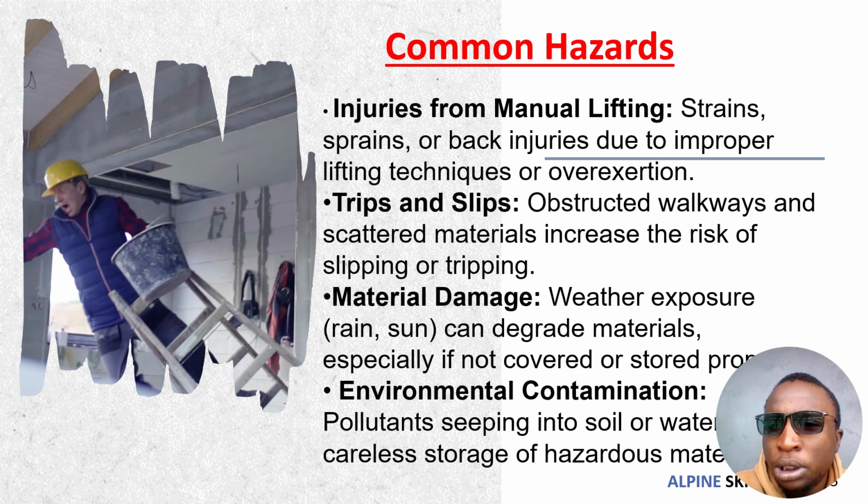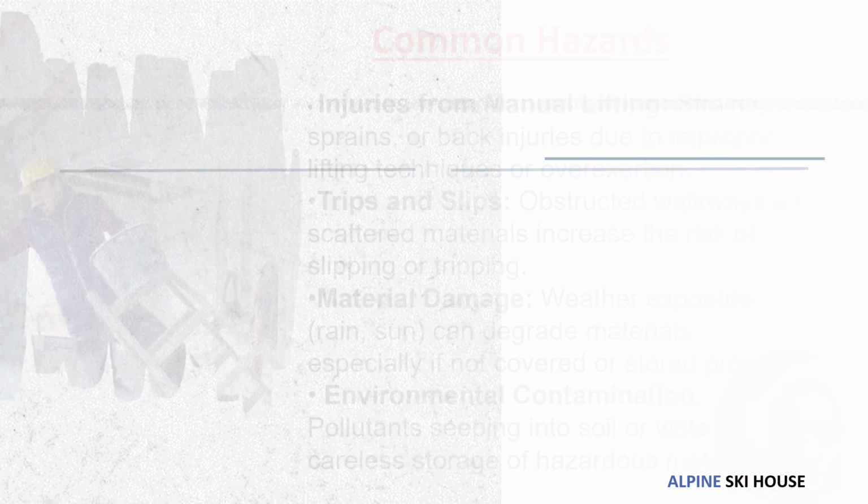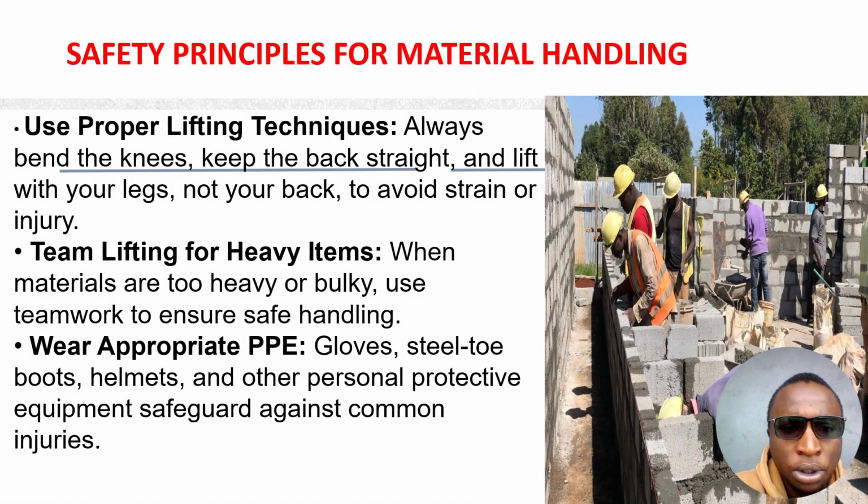The other one we talk about is the safety principles for material handling, the principles we are supposed to follow when handling materials. First, use proper lifting techniques: always bend the knees, keep the back straight, and lift with your legs, not your back, to avoid strain or injury.